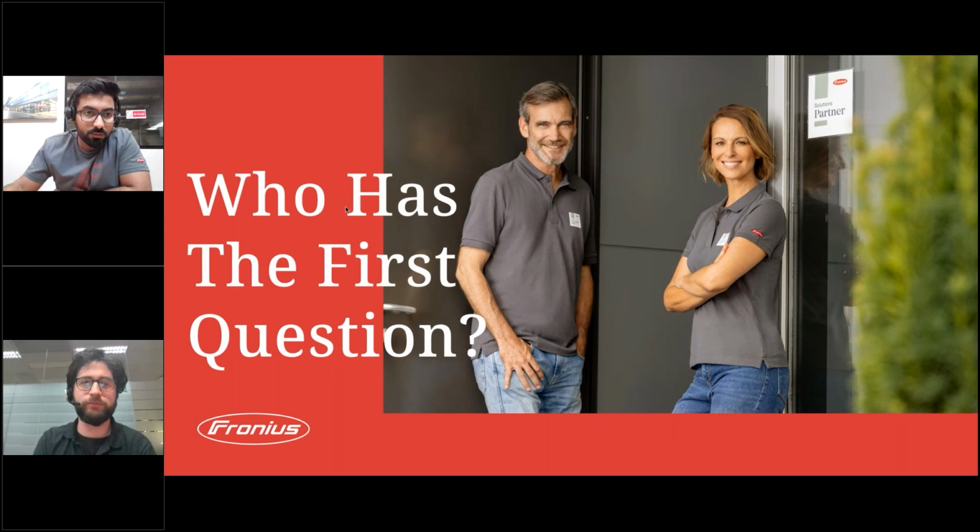Okay, there is another question, from Jackson James as well. If we, for some reason, don't know the password, is there any way to reset the password? Yes, definitely there is. We would recommend contacting your installers, because they have the tool. It's called the Fronius Solar SOS tool. They can generate a recovery key once you have provided them the challenge pin that you will be able to get after clicking on the forgot password link.